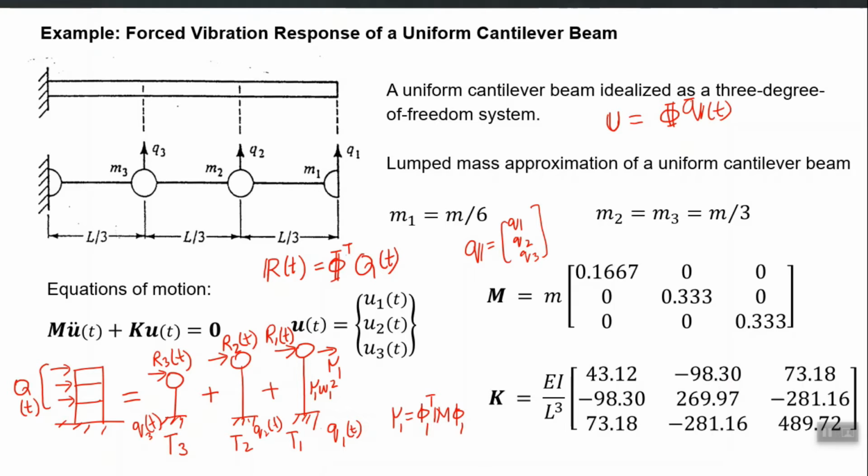So considering the fifth or sixth mode, adding it to the total u of t will not increase your accuracy much. So you only need maybe the first 3 modes or 4 modes, that is enough for most cases. Which means that only 3 or 4 modal SDF systems are required. Solving 4 single degree of freedom systems and combining their responses to get u of t may be enough for a 10-15 story building, right.